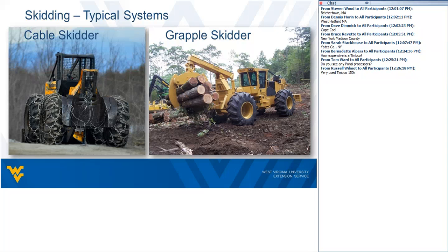It's an articulated machine. So the front section and the back section are joined with a pin sort of in the middle. And so if it wants to turn, it needs to move the entire front of the vehicle one direction or the other. The wheels don't actually turn. It's the whole entire front section there. So that's good and adds to some of its flexibility, but it also does cause a little bit additional soil disturbance while it's being used like that.